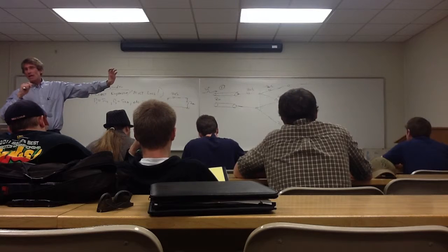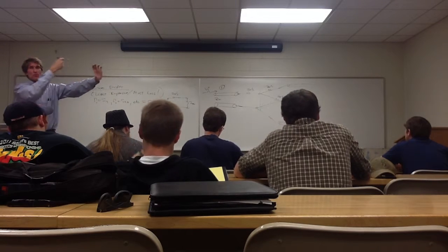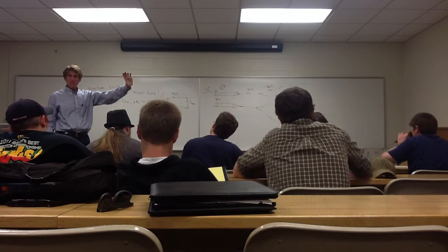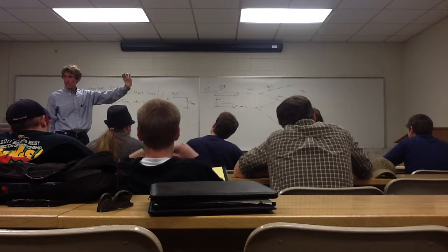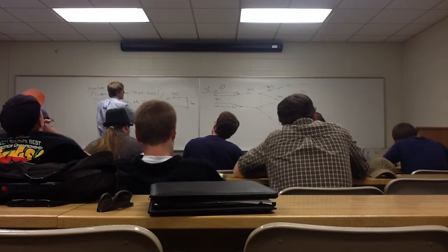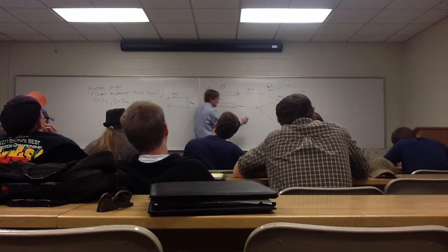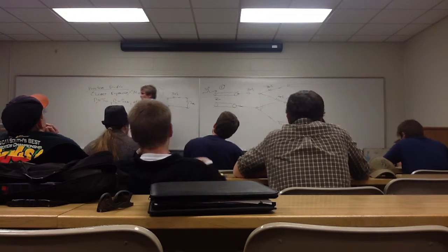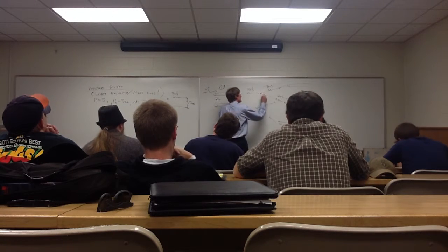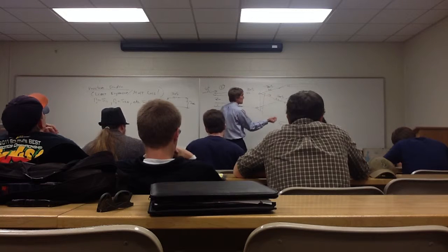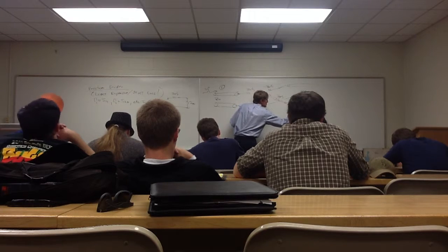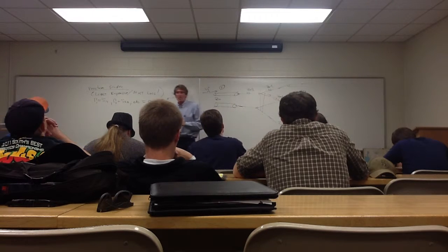Sure, if you have a coax cable, say it's 50 ohms, and you put a 25 ohm resistor in series with that, when you look into that, you get an impedance of 75 ohms, don't you? Does that make sense to everybody? Now what about this side right here, when I look this way? What do you get? Think about it. I have that resistor in series with this resistor, don't I? How many see this, class?